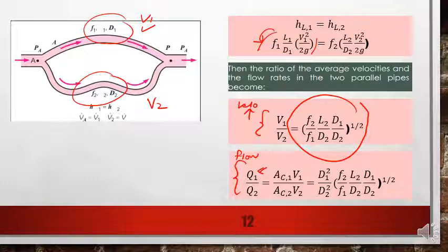If you look at here, what's the difference is you just multiply with d to the power of 2 for each pipe. Because here you add the A, therefore in the second term here you need to add the d1 to the power of 2, because we know that A is actually pi d to the power of 2. So pi can be cancelled because it's a constant.